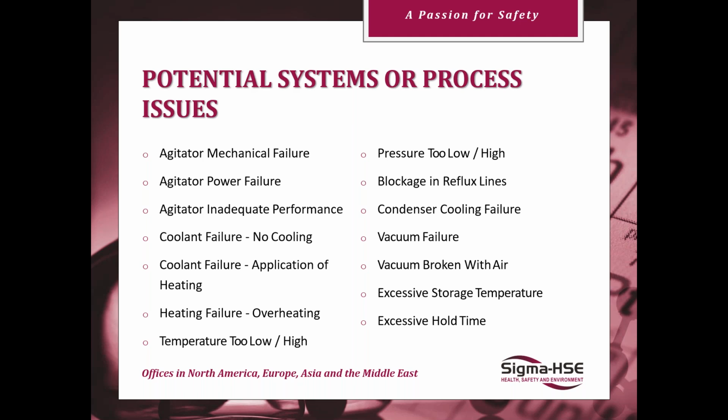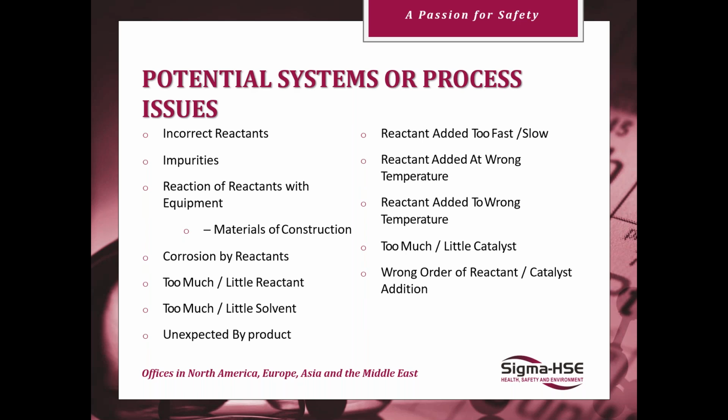That kind of non-homogeneous system can lend itself to spot heating, which can cause an issue. On the flip side of that, coolant failure, heating failures with overheating, like the steam example, temperature, pressure, blockages, which will increase the pressure, especially in the reflux line, condenser, vacuum, storage. All of these are many reasons that might cause a runaway.